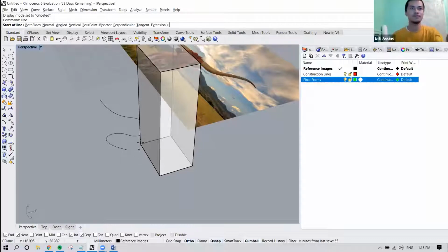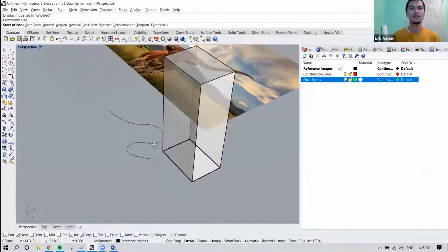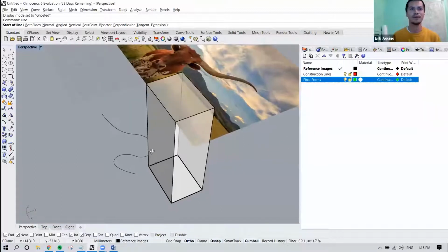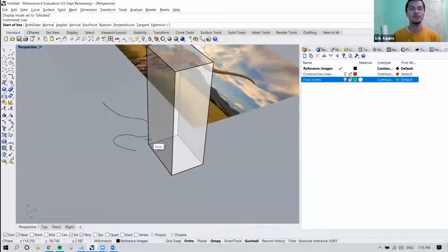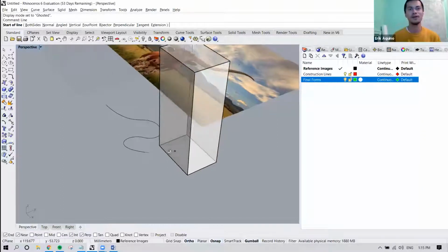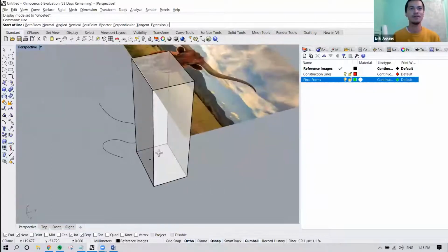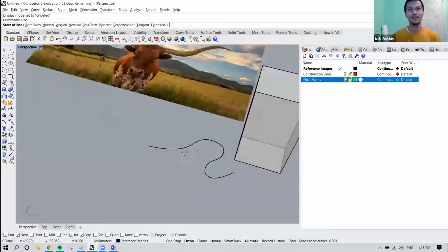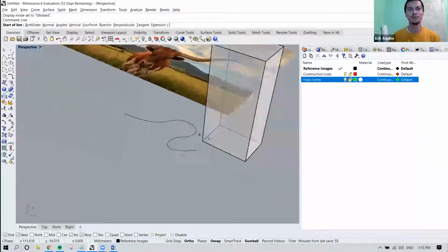And so now I could snap to this apparent intersection, although if you were to change the view, then there's really no constant anchor between the two objects other than you being able to visually see them intersect. So I would just advise you to be aware that that may be an option for you to select, but it's not the best because it's not a physical intersection between the two objects.